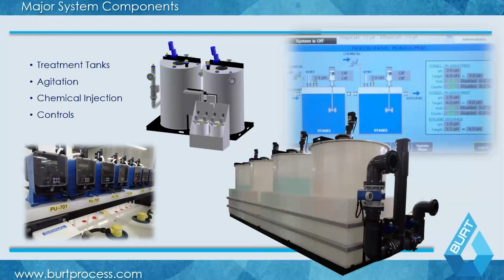The major components of a pH neutralization system are the treatment tanks, agitation, chemical injection, and controls. As I mentioned to you before, you see here a couple different examples of each one of these. You have your treatment system here. It's a 3D rendering. This is a two-stage system. And in a typical flow-through design or even a hybrid style design, this is what's referred to as having more than one stage as part of your system.